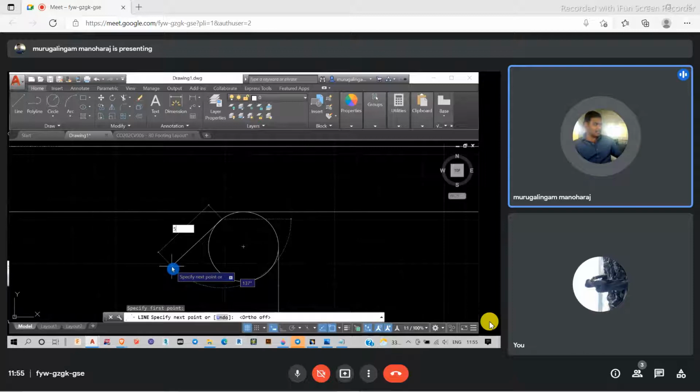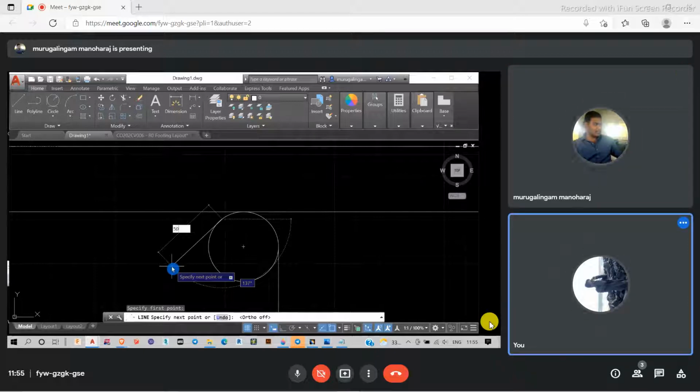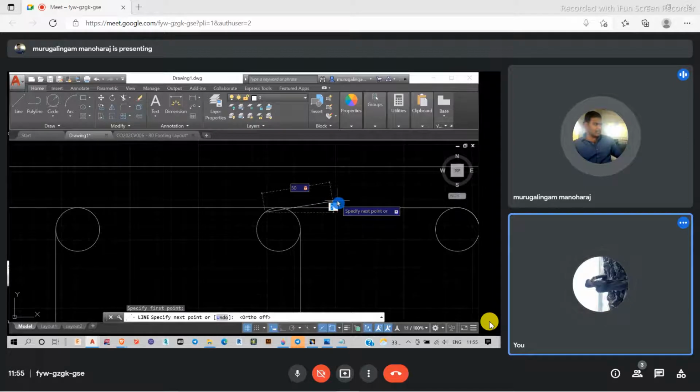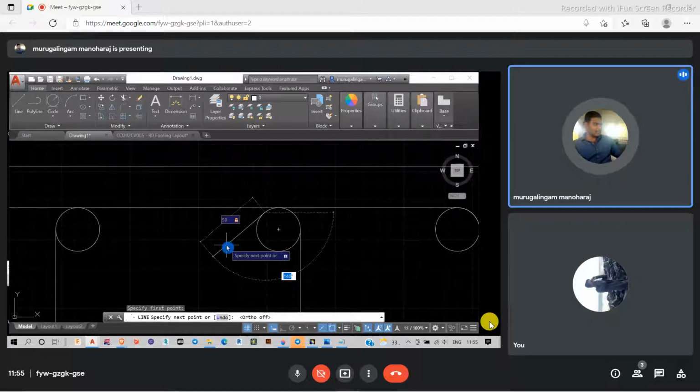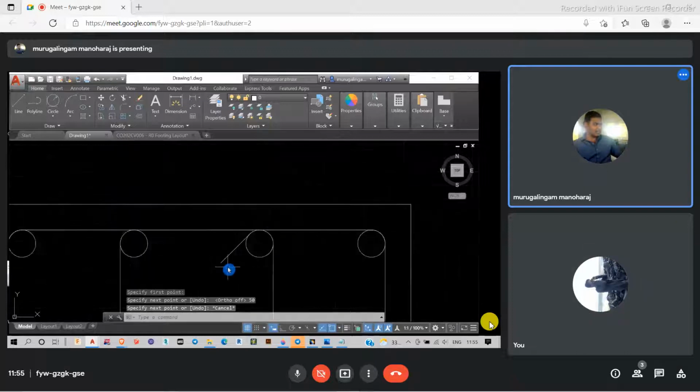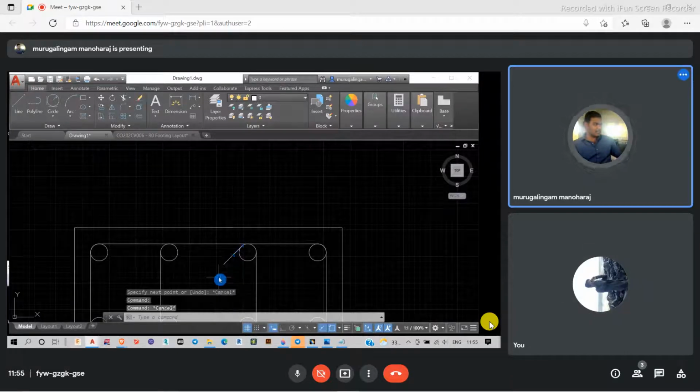I will show you how they are giving the 50 mm and how to calculate those values. I will show you a book as per the Indian code. And since the angle will be calculated from the anti-clockwise direction, I have to give an angle of 135 degrees, 90 plus 45 degrees. A 45 degree hook has been created here.